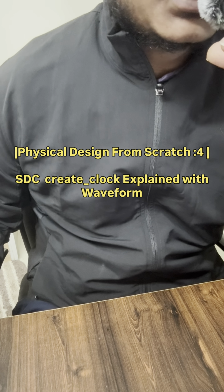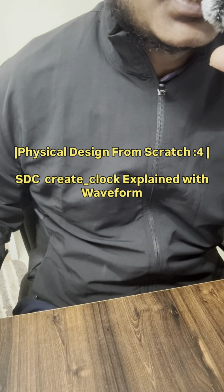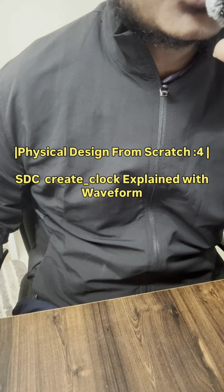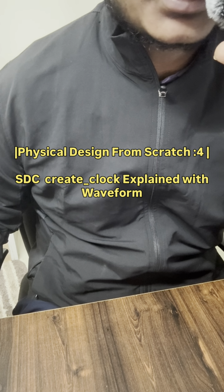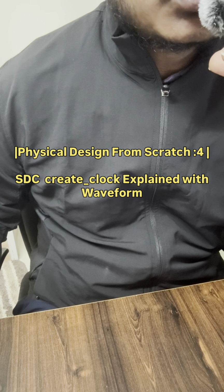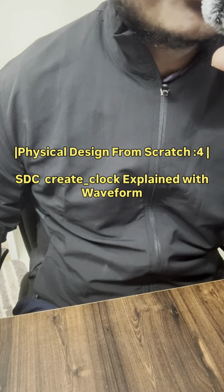The timing analysis of the design depends on the clock because the setup and hold checks are related to the clock edges. Therefore, we must specify the clock information to the timing tool using the create_clock constraint. According to timing analysis methodology, the clock definitions are provided as a part of the external environment using SDC constraints.